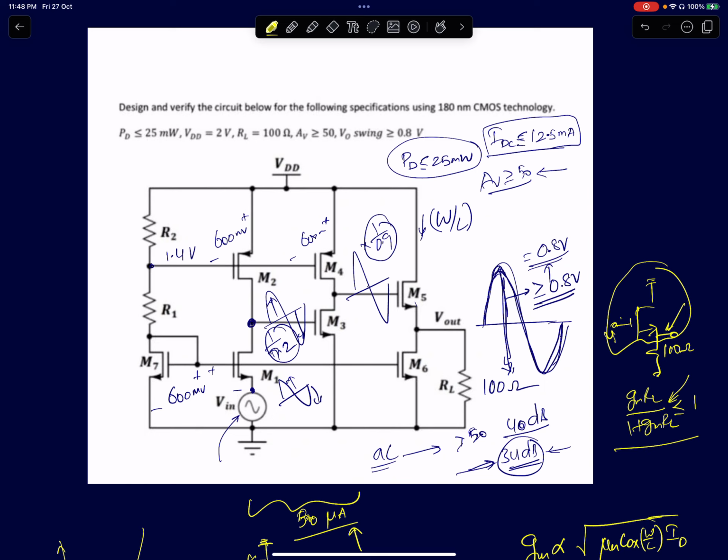There is one problem with this circuit. I wouldn't design a question like this. There is a problem with biasing single-ended amplifiers. When you drive a current source load, the biasing is usually quite problematic. Even when you're analyzing this, when you tweak some small W/L ratios here and there, you will see some sudden weird changes at the output. I'll explain why that happens in a later video.